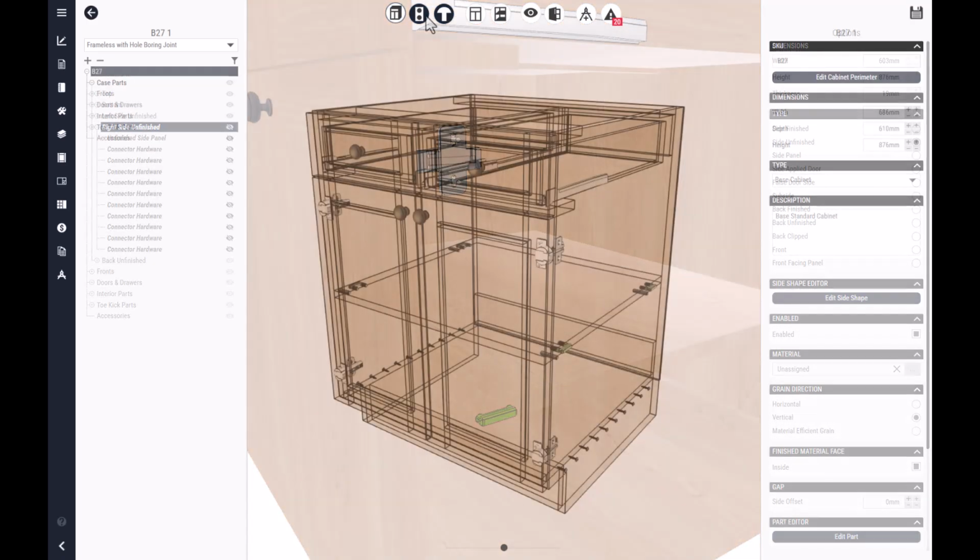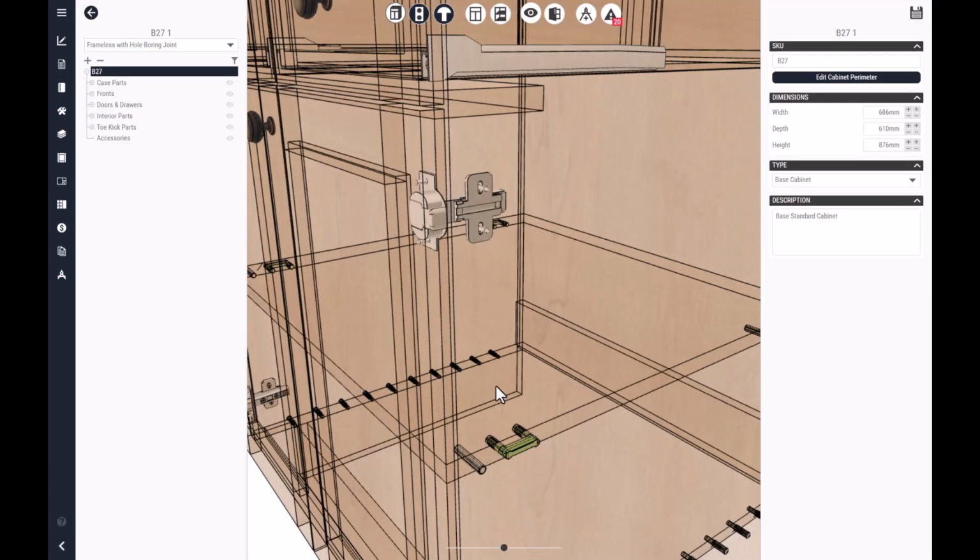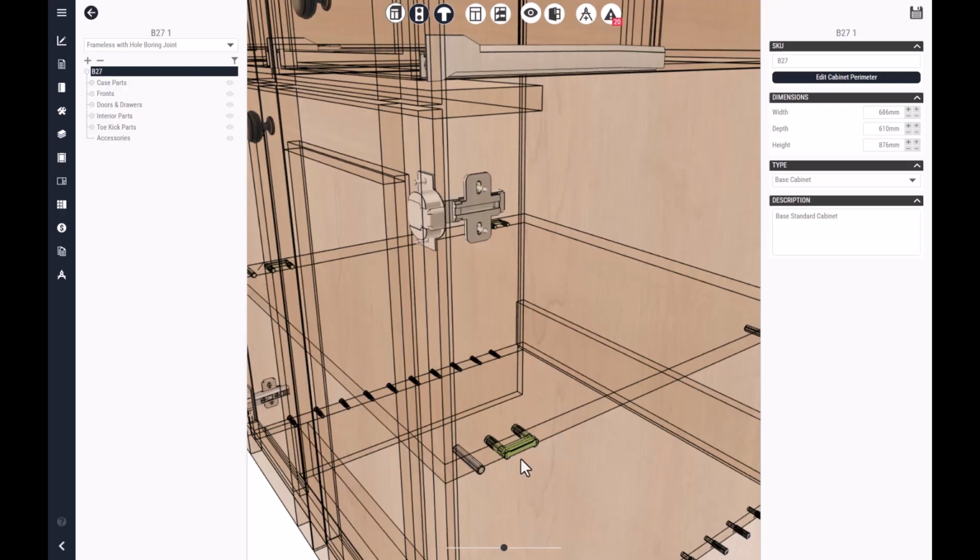For H-clip, we can verify the routed H-clip channel and confirm that the flexible locking tab engages the channel when the parts are pushed together. When spring pin machining is enabled, also verify the spring pin position, the spring pinhole dimensions, and the added shear strength of the completed joint. For either connection type, also verify the center's arrangement, end center position, center quantity, parts gap, and selected connector materials.